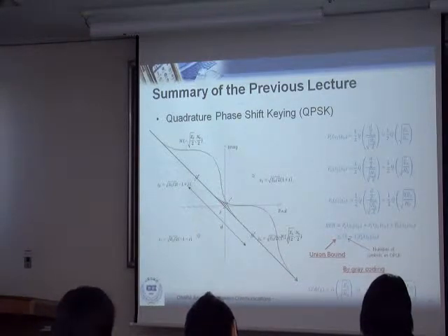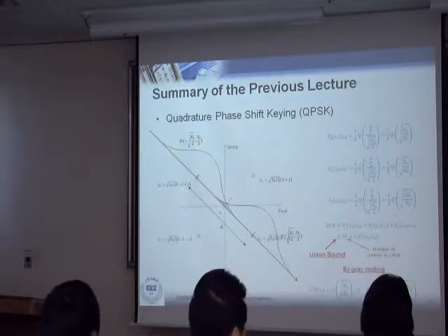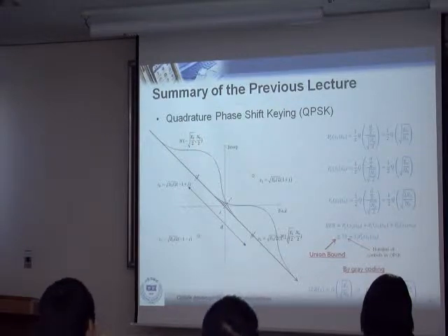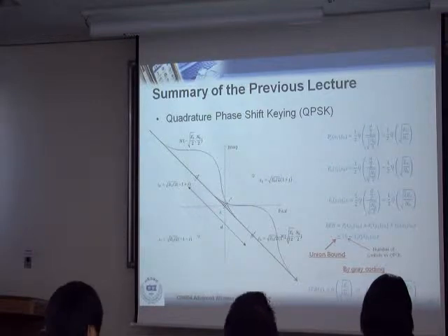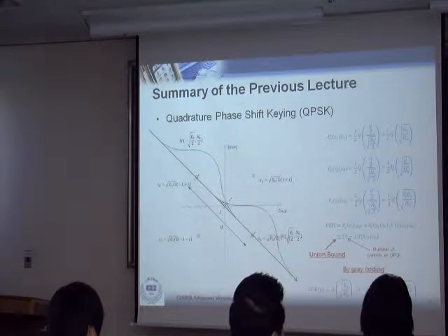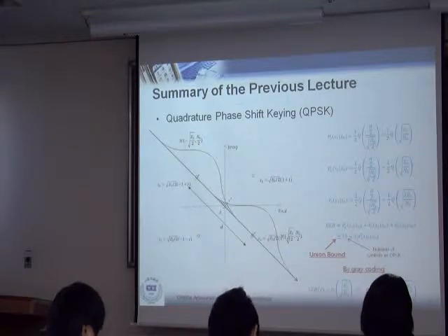Once you use Es over N0, that basically means I want to look at the symbol error rate. That's why I said Es right here, right? That means I want to see the symbol error rate. In that case, let's say we have this curve. Now I want to overlay another picture, and in this case, I choose Eb over N0. Therefore, I want to see the BER. And I want to plot these two on the same picture. Okay, once I do that, how does it appear?